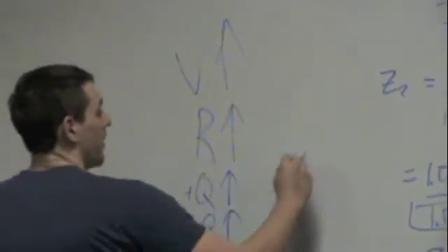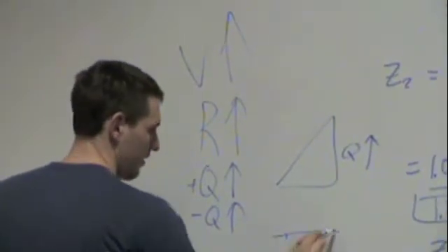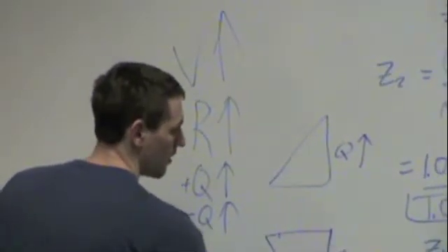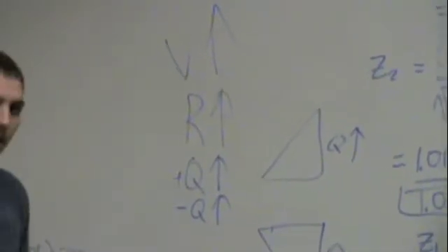Based on the sign convention I've used in the past, the inductor Q is positive, and Q from a capacitor is negative. If you do it the other way around, you get the right answer anyway. So in this case, we have an inductive source, so we need the negative version, which makes him right.